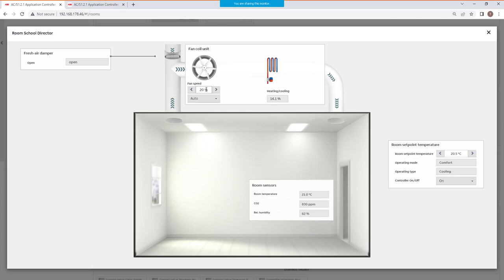It's a real action, of course, in the fan coil controller. And the fan speed is 20% at the moment, and it opens here around 14%. So I go down a bit more. It increased, of course. Okay. So you see directly what happens if I simulate now.